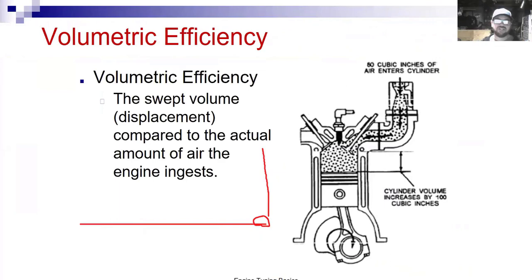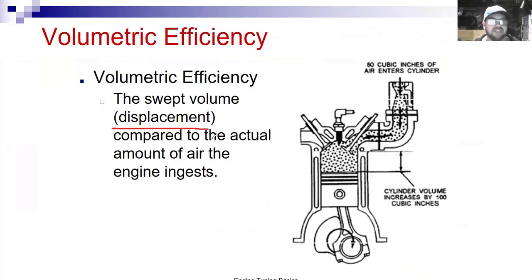Well, volumetric efficiency really is comparing how much air has entered the engine for real versus theoretically how much air should be coming in there. The swept volume or the displacement, right? You guys have probably heard that saying, there's no replacement for displacement. The displacement of the engine is its internal size. If you think of your engine like a pump, how much air would it pump out? So maybe I have a 5.7 liter V8 engine, right? That's a 350 cubic inch engine. So that would be its displacement.